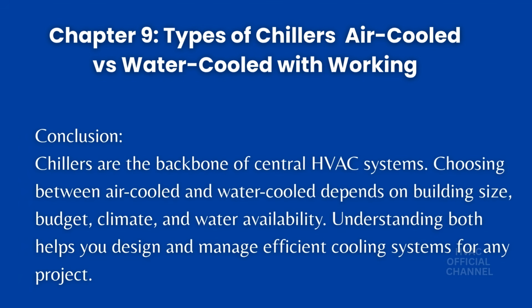Conclusion: chillers are the backbone of central HVAC systems. Choosing between air-cooled and water-cooled depends on building size, budget, climate, and water availability. Understanding both helps you design and manage efficient cooling systems for any project.